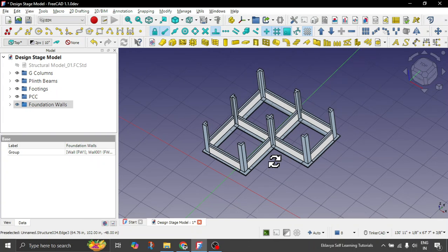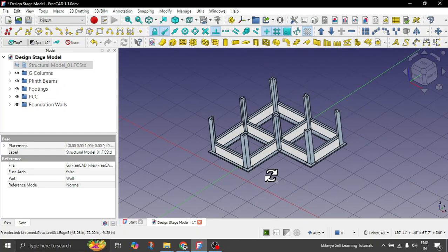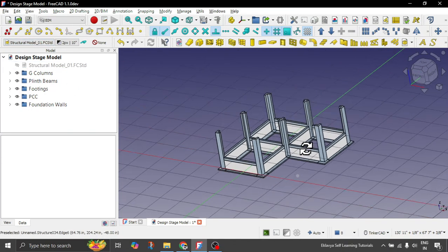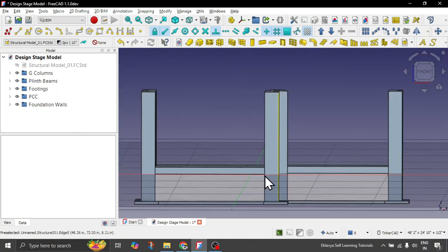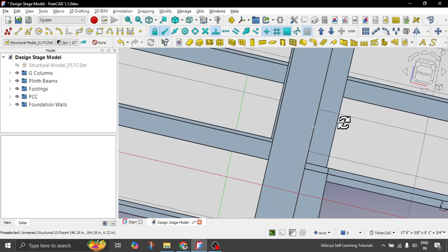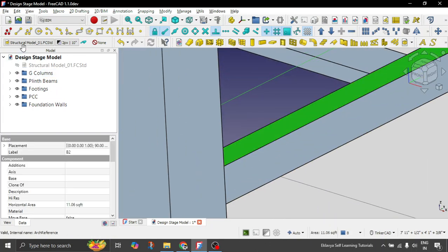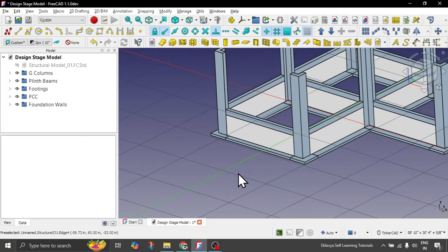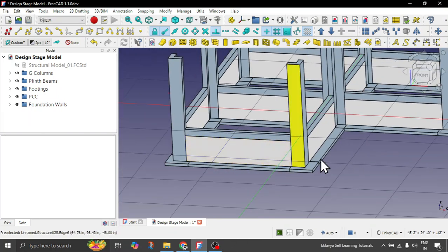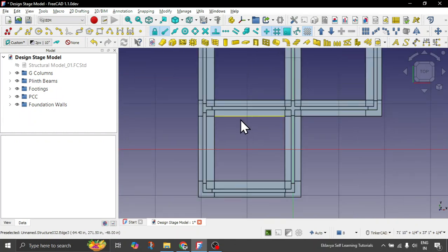So this is the boundary wall, right? Now what you can do is create the ground slab. Let's switch to the top view, which is at 0, 0, which is here, right? And the slabs we want parallel to the plinth level basically. So plinth beams are, let's select this and let's just choose this one. Yeah, so this is the working level at which we want the slabs, right? We'll extrude them downwards, and we will use this boundary. So these will be now quite easy rectangles.